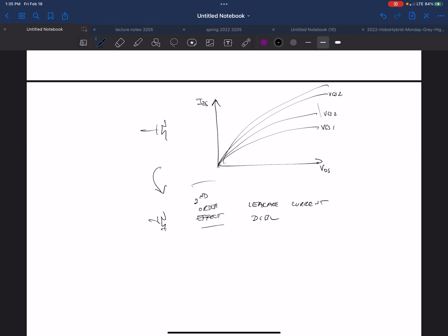If it's not transitioning, it's not burning power, so that was what made it popular. Well, guess what now? You do burn power when you're not in transition. By the time you have 20 billion transistors, each one has a tiny bit of leakage. You multiply it by 20 times 10 to the 9th and you end up with amps of current, which is a serious problem. We'll talk about that.